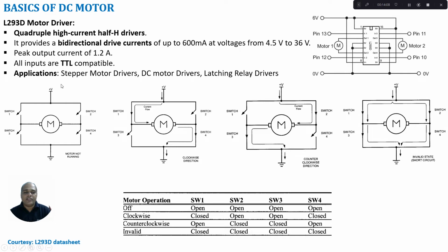The applications for this motor driver IC are in stepper motor drivers, DC motor drivers, and also in latching relay drivers. When we see the pin details of this L293D, here I have shown the connection diagram of L293D with your microcontroller. Essentially we can connect 2 motors to this L293D.